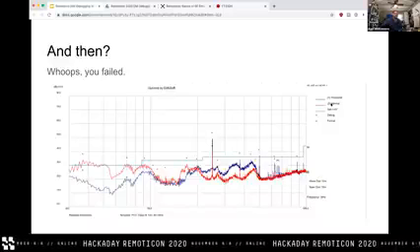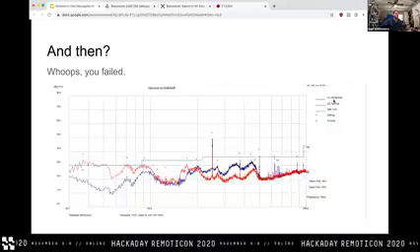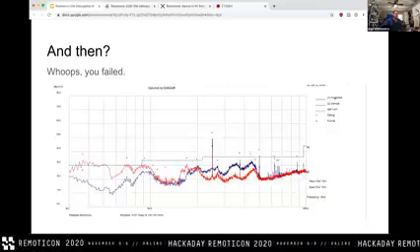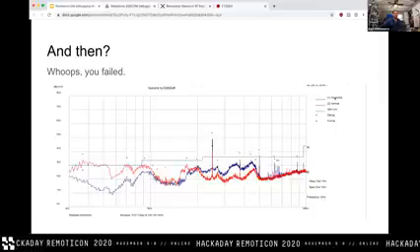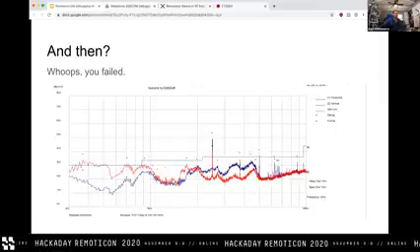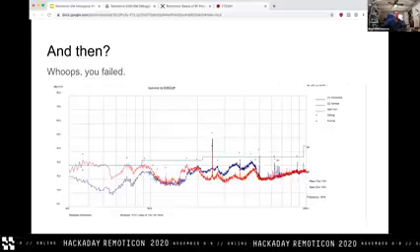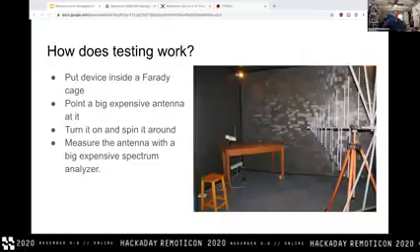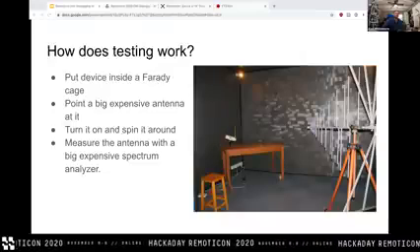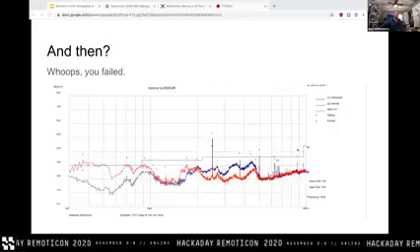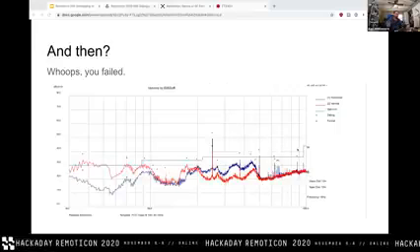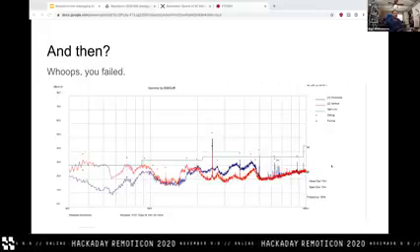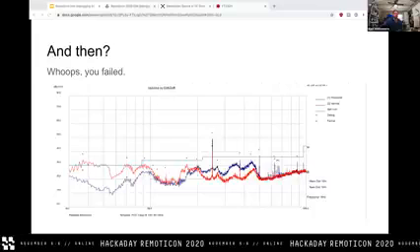That antenna, being an electromagnetic device, has a polarization. It's, I guess, horizontally or vertically polarized depending on the physical orientation of the antenna. In the last slide, you can see that it's clearly got some asymmetrical geometry to it. So one of these lines was taken with that antenna rotated vertically, and one of them was taken with that antenna rotated horizontally, and you have to pass both of those tests in order to pass your test.